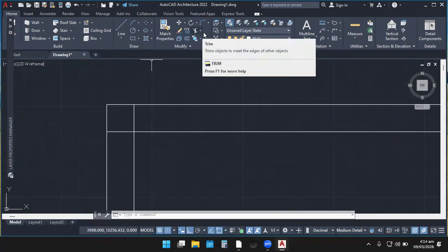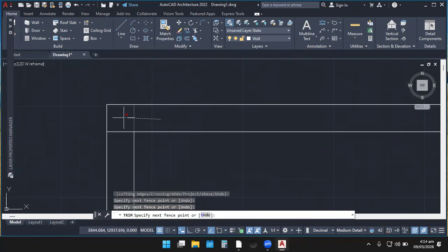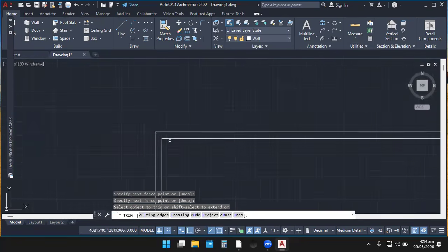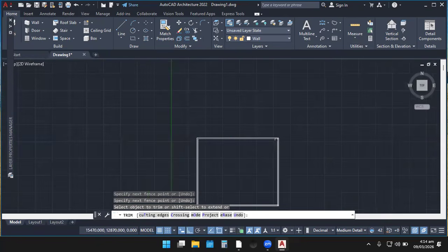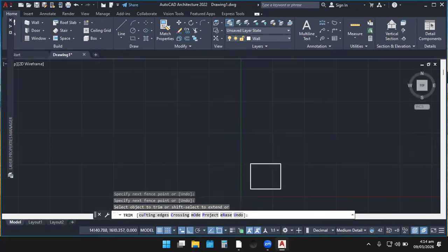Come over here. You see this? This is trim. You click the drop down menu and select trim. So I click an empty free space. I drag inward. I click to release the mouse. You trim all these places nicely. You come back, bring the mouse to that point and zoom. It will come for you. So I'm trimming all these places.